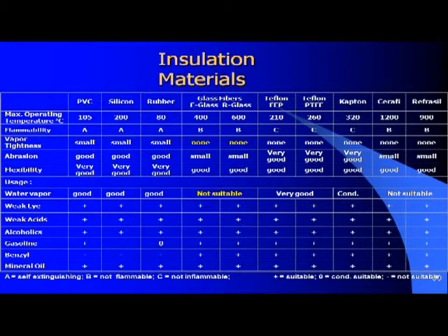Yes? Silicon is a good idea, always. It is stable, for example, against sunlight, as well as Teflon is stable against sunlight. Rubber is not stable against sunlight. You cannot use it in free air installations. You should not use it.